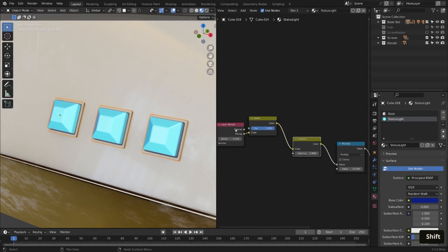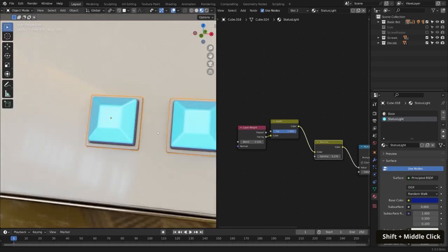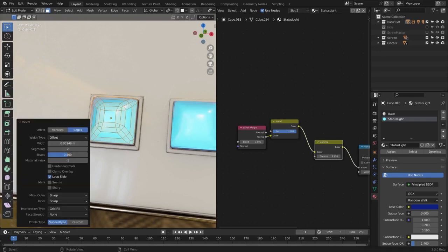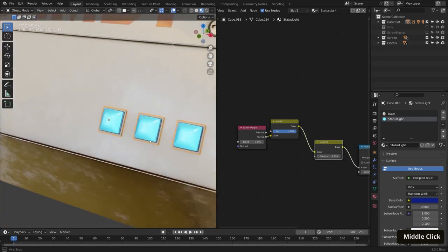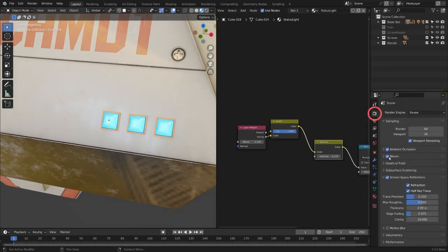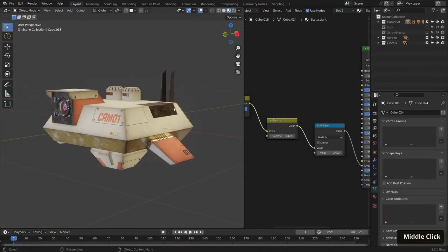Now, in order to fully take advantage of this layer weight, it might even be worth adding a little bit more geometry. So if we go into our light with the Tab button and just select our top polygon and again expand it with Control and plus, and then Control and B to add a bevel. Okay, let's commit to that. And now you can see you get much more of a nested emission type of vibe. And that mixed with a bloom effect, I think will work very nicely. Yeah, that's looking nice.